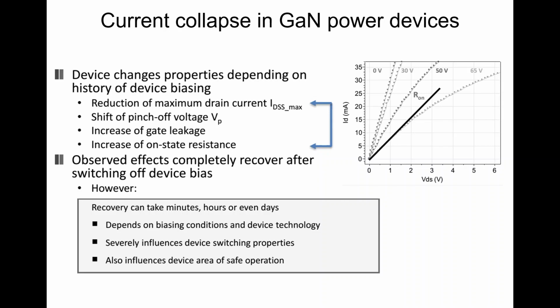And depending on the origin of the problem, you can also have a shift of pinch-off or increase of leakage. The recovery, because these are memory effects, can take minutes, depending on the time constant of your traps, hours or days. And I think everybody working in this field for a while has seen that, because things were not really well understood at that time.